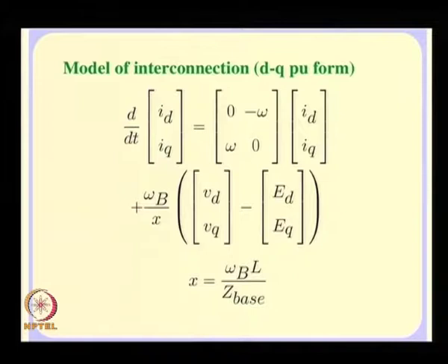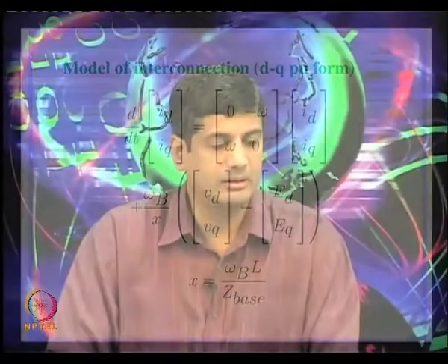And if we do use these differential equations as well, we have to be really careful to be consistent, in the sense that you cannot give I_d and I_q, for example, initial conditions for these differential equations which are inconsistent with what you would obtain when you get the currents algebraically related to the fluxes. So, all the initial conditions would need to be absolutely consistent.